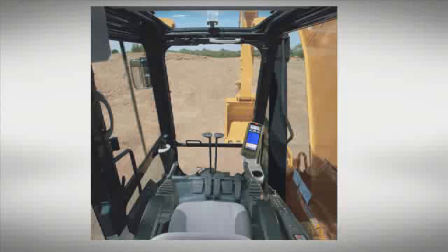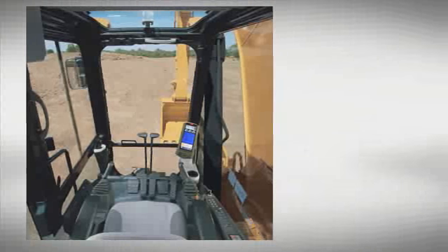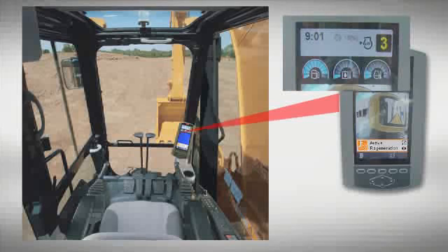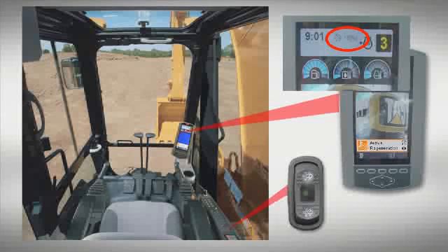The operator interface on CAT hydraulic excavators consists of the liquid crystal display that now includes the various regeneration indicators such as the Regen Active lamp, Regen Disable lamp, and DPF lamp. The DPF soot level appears above the gauges at the top center of the display. On the hydraulic excavator, the bar graph style soot gauge is replaced by a numerical percentage from 0 to 100%. The manual disable regeneration rocker switch is located on the right-hand console.